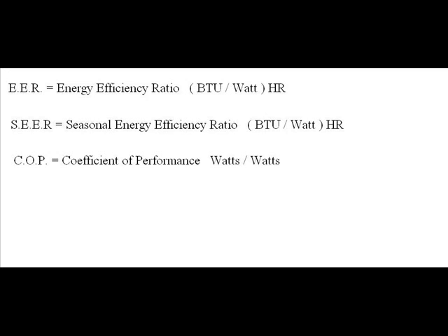We actually have a rating in EER, for energy efficiency ratio, which allows us to quantify how much heat energy in BTUs we are moving per supplied electrical energy in watts per given hour. In a lot of air conditioner units, you actually see this represented as a SEER, which is a seasonal energy efficiency ratio, which is the anticipated yearly average of the different seasonal conditions of that heat pump's instantaneous or shorter-term hourly EER rating.